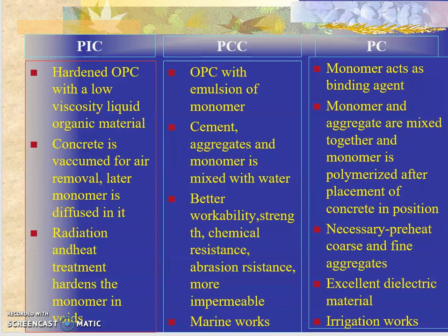And now, if your requirement is such that you cannot afford to have any voids in this concrete, then you take this hardened concrete element and you keep it inside the solution of polymer. The polymer can be any acrylic material or anything. These materials are in solvent form.